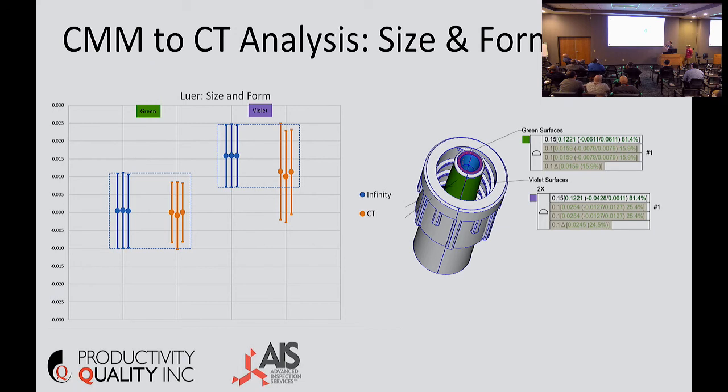So the CT scan, we saw the panel detector. That's just a panel detector like you have in a video CMM, right? It's just a 2D array of pixels. So we can compensate the size of those pixels at different magnifications. So we might have a size bias that we need to correct going forward in our CT.